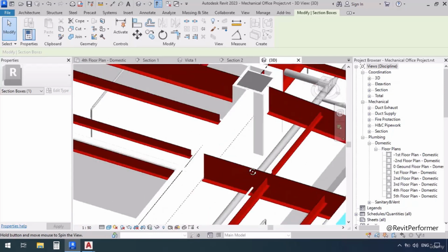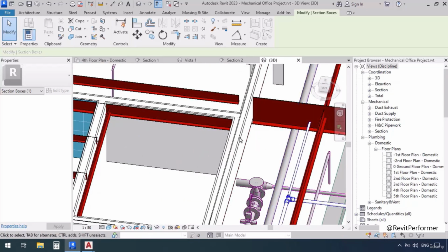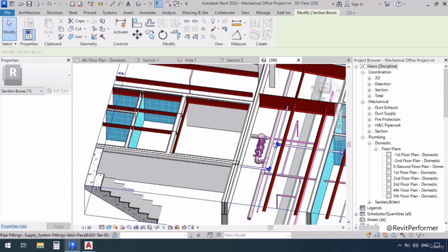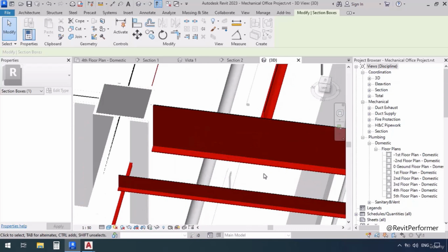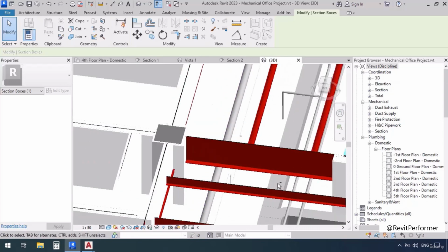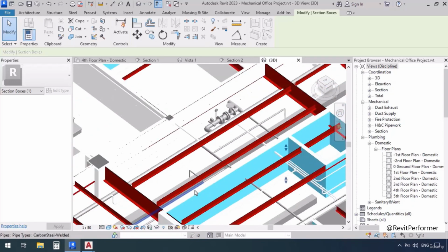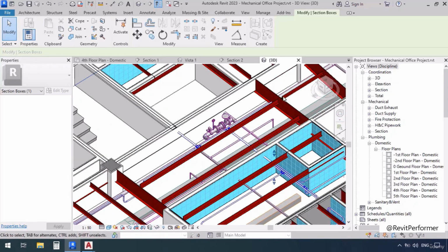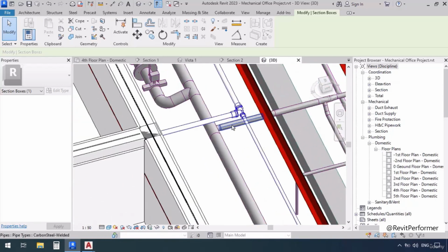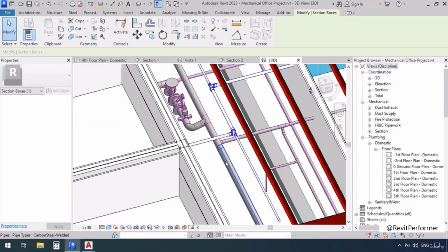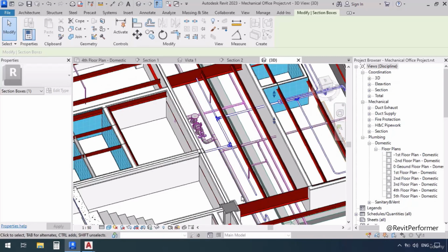In that case, you can see another beam in the way, and the pipe would go through it, but it's best if we draw the pipe at a lower elevation. And also on this side, let's expand it. Let's take a look. I have bent this pipe downwards. So what I'm going to do is change this entire line's elevation to something lower. What will happen if I lower the elevation? We will have an interference with this fire protection pipe. So it's best if we bend the pipe only at this point.